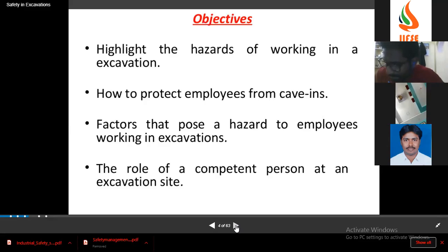No problem. What you have asked is, before going into the confined space, based on the precautionary measures, the first thing to do is to take a multi-gas detector and test the gases. That is the first primary thing to do, and we will talk about this when we discuss the precautionary measures. What are the hazards in confined space, sir?